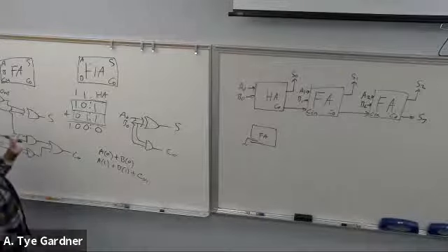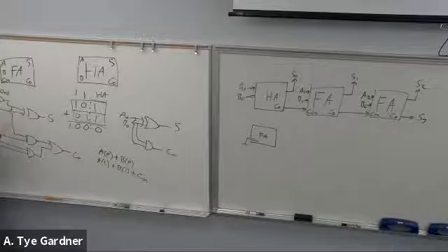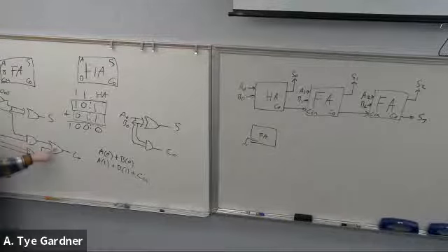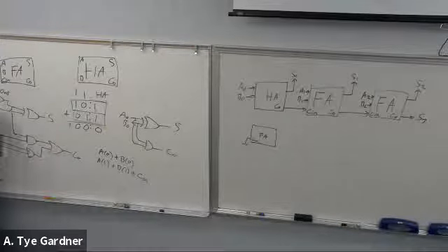So the gate delays, if we do the simple but bad version and just say they're all 10 nanoseconds. Well, then in order to get my first carry out in this architecture, I have 10 nanoseconds plus 10 nanoseconds plus 10 nanoseconds. So what I'm looking for is the longest path. In this case, 3 gates or 3 gate delays.